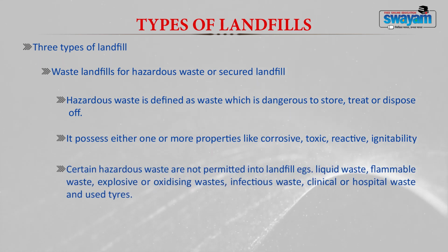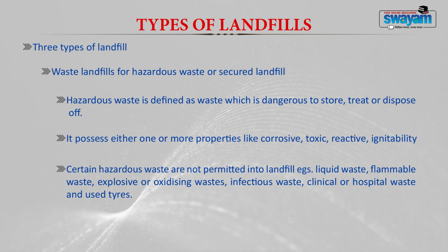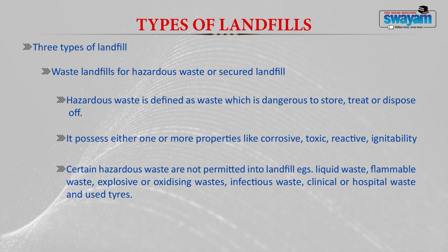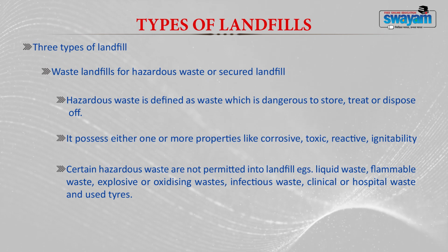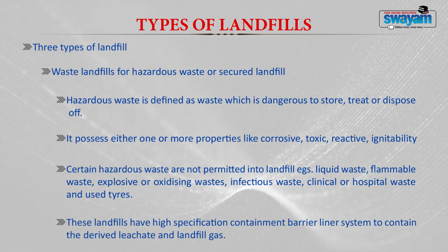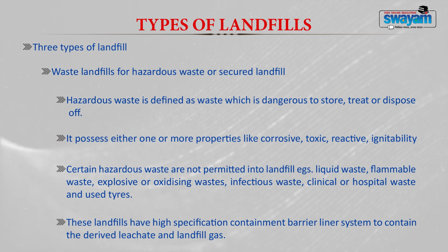Certain hazardous wastes are not generally permitted into landfills. Some examples are liquid waste, flammable waste, explosives, oxidizing waste, infectious waste, clinical or hospital waste, and used tires, which are not allowed in a secure landfill. Now, these landfills have a very high specification contaminant barrier liner system, to avoid leachate entry and landfill gas emission, because a small contamination will lead to a very big health and environmental hazard.